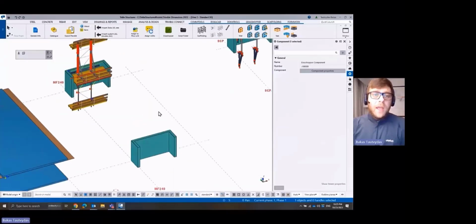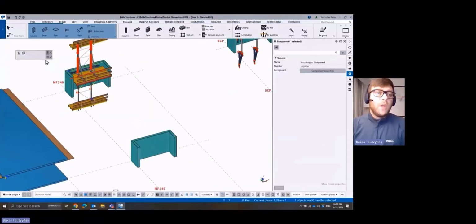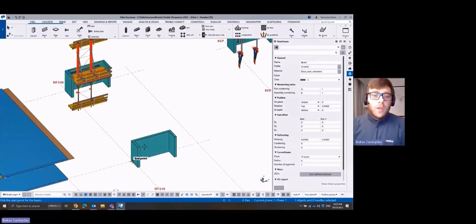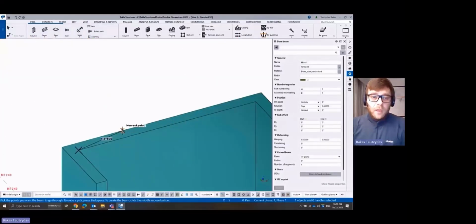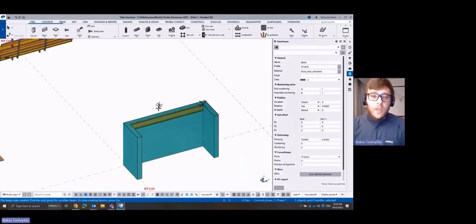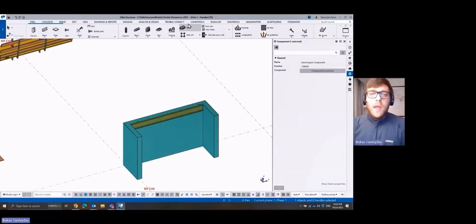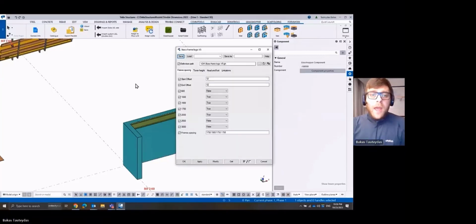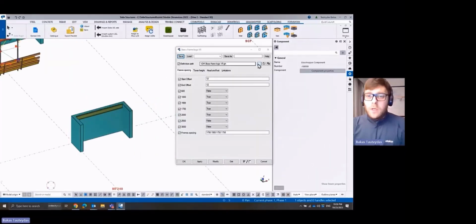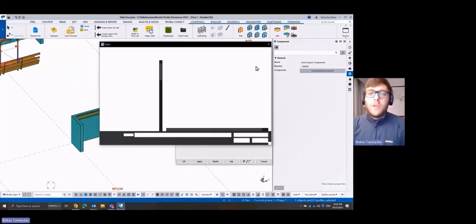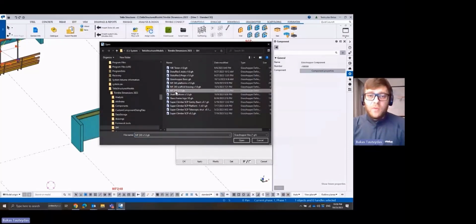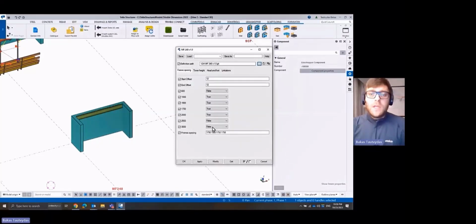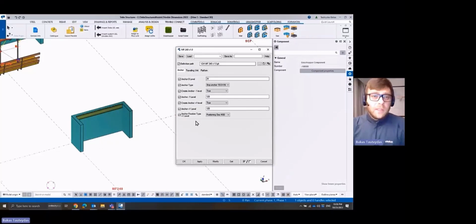To insert the Grasshopper script, first we're using a polybeam. So let's snap very fast the edge of a wall. Where is my first bracket? Where is my, let's say, second bracket? And the end, middle mouse button. I just get a polybeam and I come in here. Where is Grasshopper? Double click. And to choose Grasshopper scripts, I can click the three dots and find MF240 here. And let's wait a few seconds and it will load the interface here.